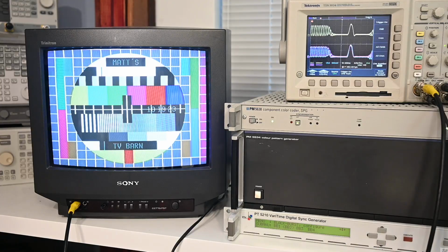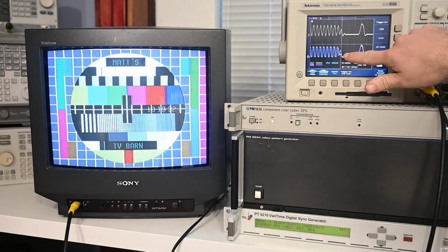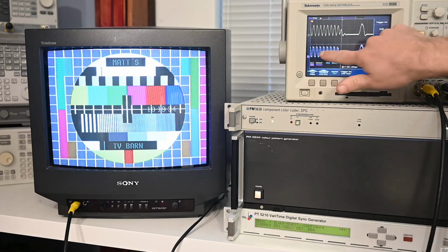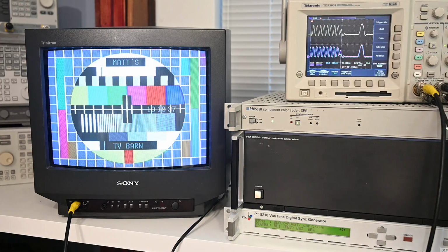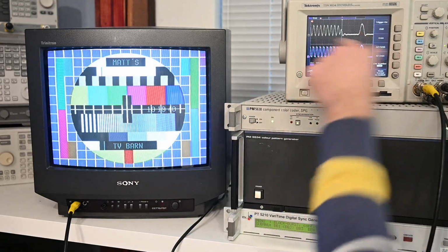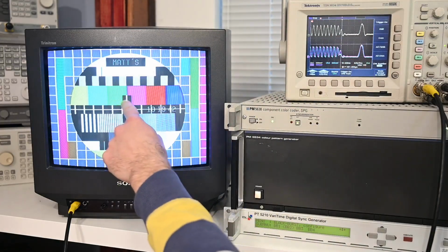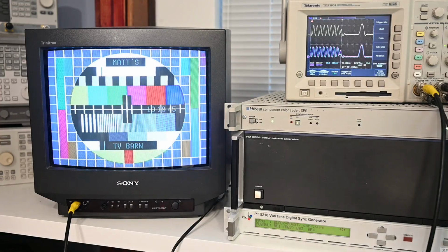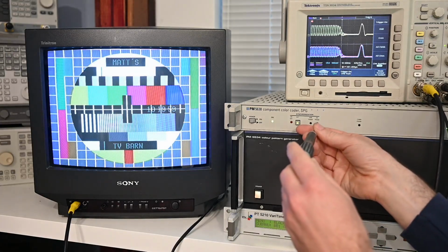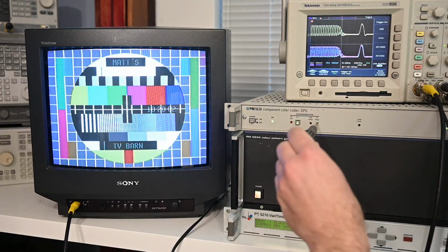Now if we actually have a look on the oscilloscope here, we can see that phase error straight away. I'll just scroll across here. So remember that the purple and blue are our two inputs, and you can see that they're not aligned. Now the feature that we're looking at here is that pulse there, this white line, and this is that piece of green there. Now I do apologise, I don't have a vector scope, which is how you would normally set this up, but we can sort of do this on the oscilloscope. So if we run this again, and we'll just jam our screwdriver into this subcarrier phase screwdriver hole here, and just rotate it around.